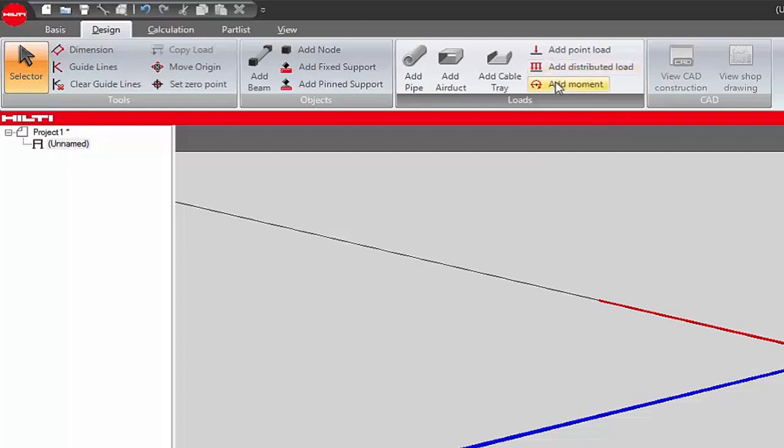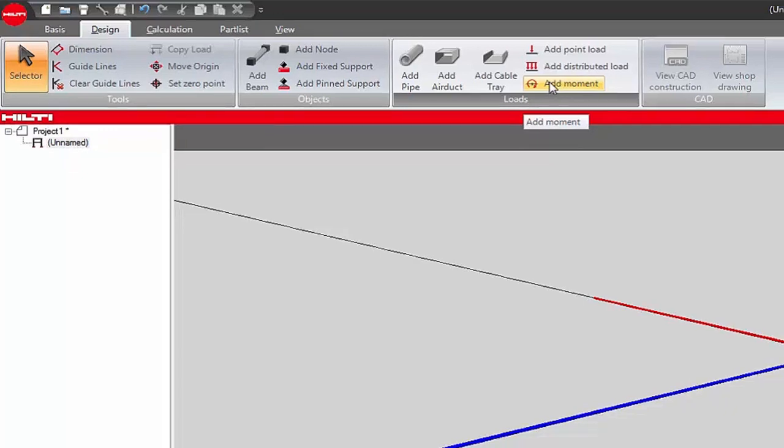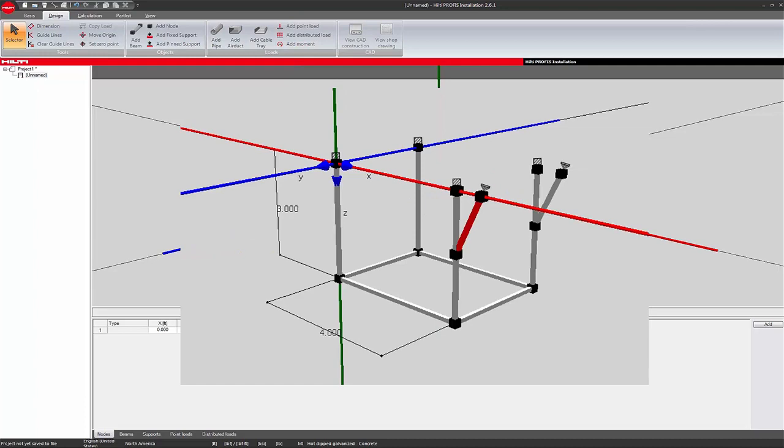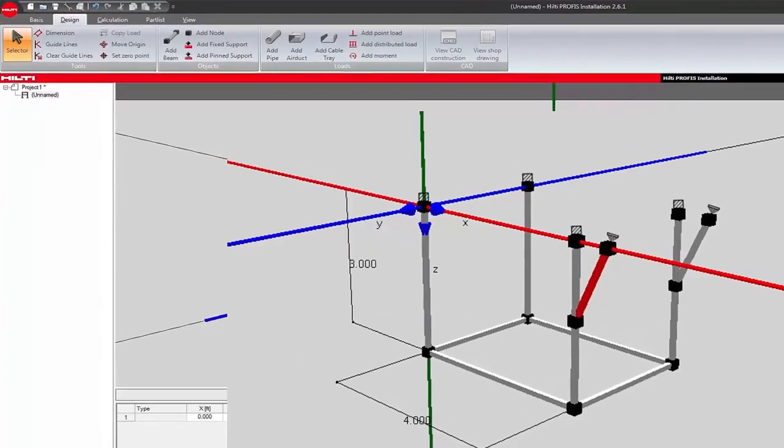Add moment load. You have the option to add dead, live, earthquake, seismic, wind, and/or snow moment loads to the design application. For this example, we will create a suspended platform with dimensions of 3 feet by 4 feet braced on one side like the one shown.